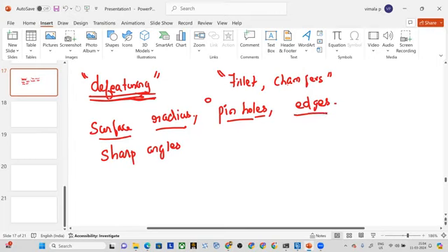And a few of the edges which also have very minute radius and sharp angles. These are all the things which actually make your meshing process fail. Without meshing, you will not be able to apply the boundary condition and loading condition to find out the results, right? So you have to get rid of all these things before entering into the meshing part.